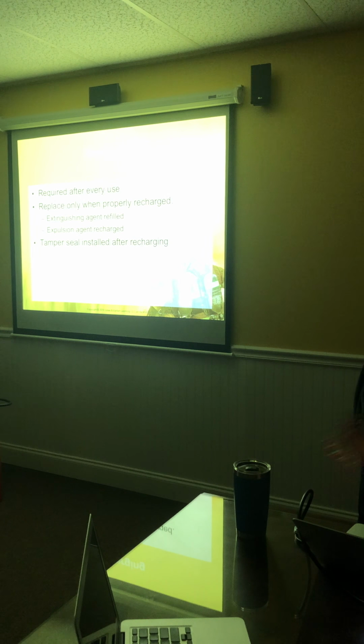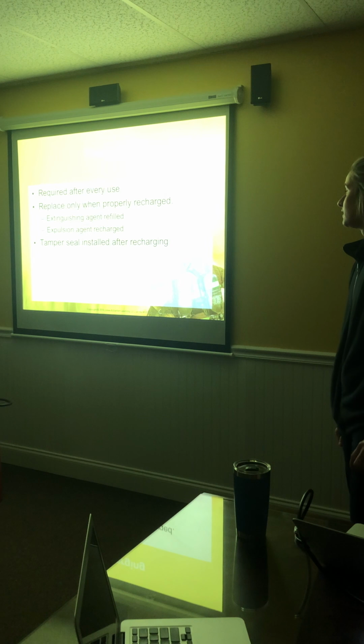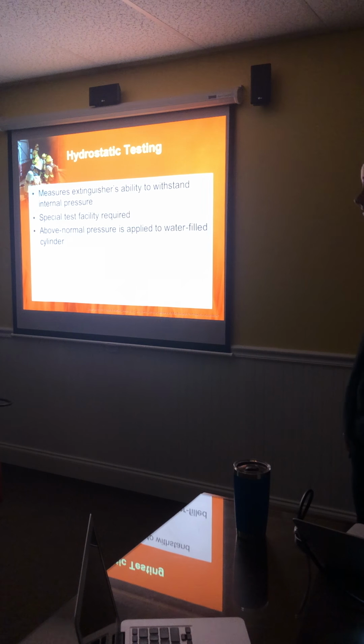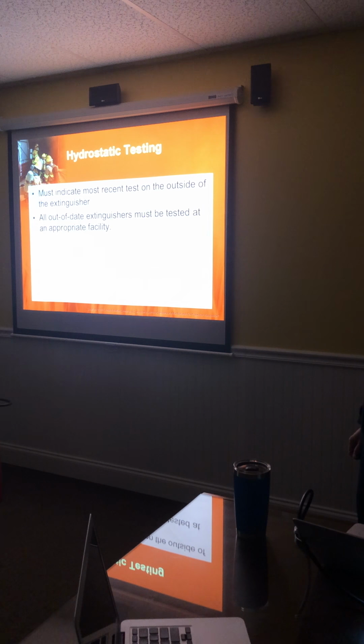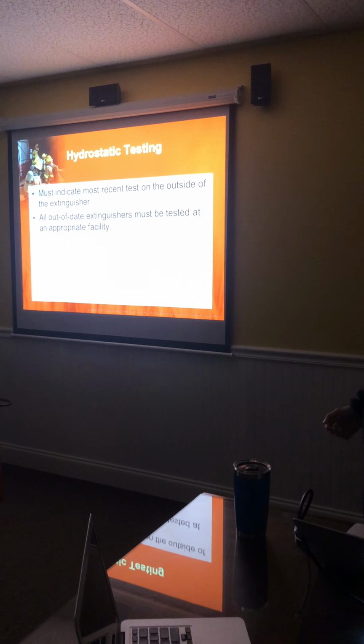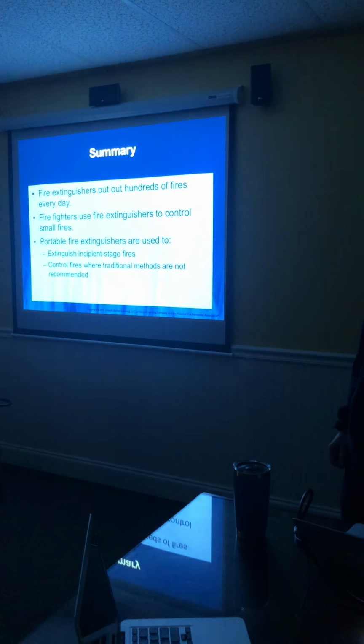Recharging is required after every use, and replace only when properly recharged. Hydrostatic testing measures the extinguisher's ability to withstand internal pressure, and there's a specific test and facility that's required for testing. There's a little tag or sticker on the extinguisher that must be recent and up to date.